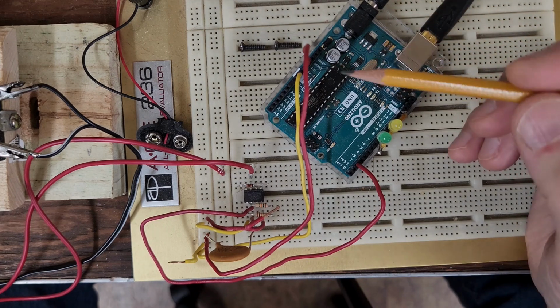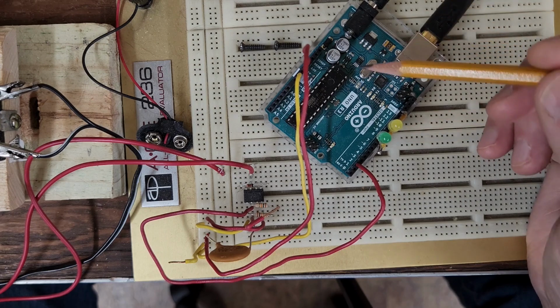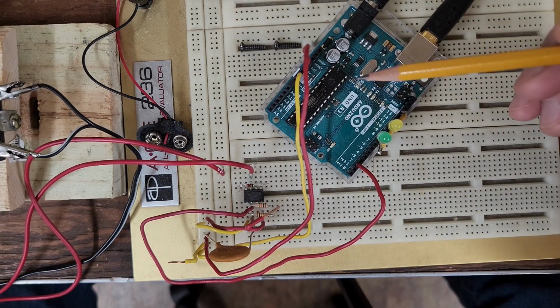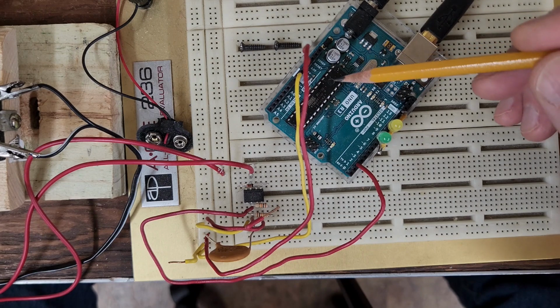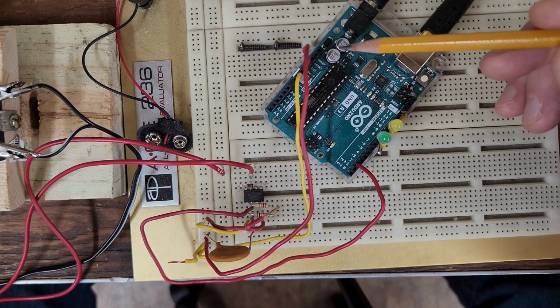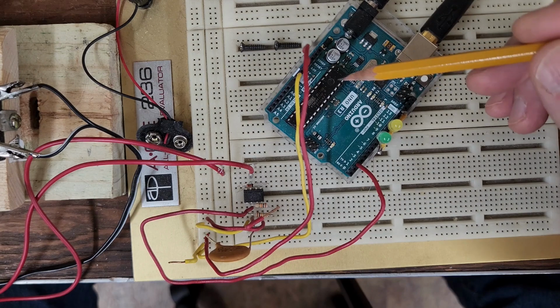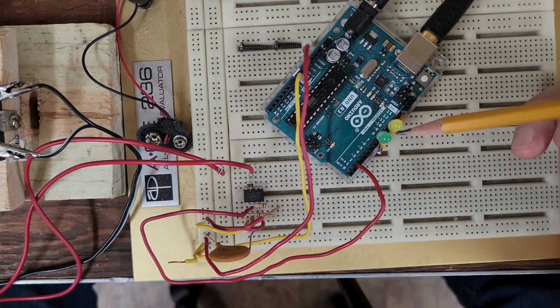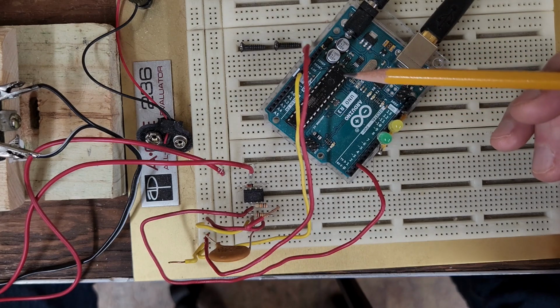In order to debug code, that's why I added 2 LEDs to this Arduino, because you don't have an in-circuit emulation capability with these Arduinos, at least not to my knowledge. So some really crude troubleshooting techniques are inserting breakpoints, which are actually stop loops that turn on a particular sequence of the LEDs and blink them in a certain fashion so I can understand what the actual code is doing.